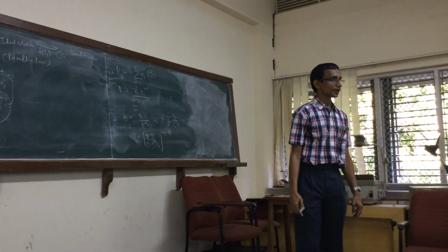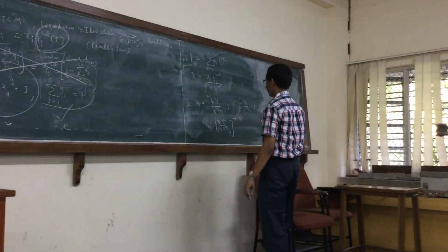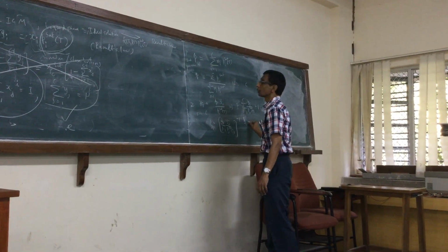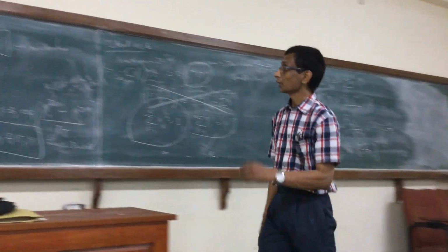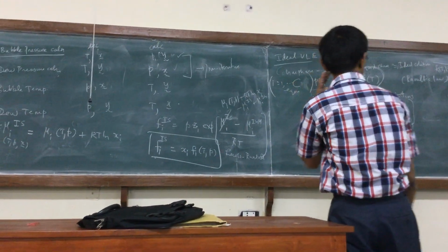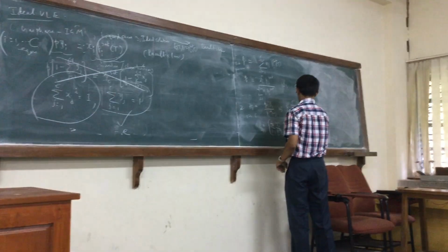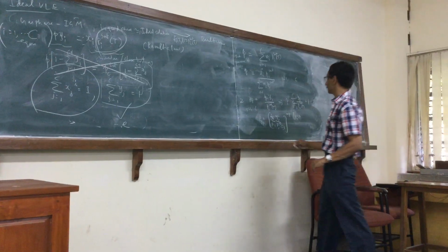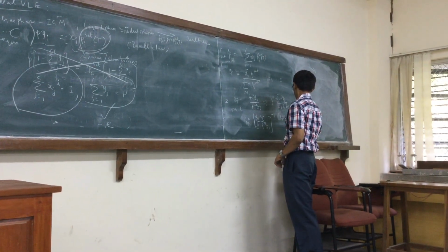Once the specification is given, the dew pressure can be found, and then the xi, which we don't know, I'm sorry, the y is known, the x, which we don't know, can easily be calculated by P times yi by Pi sat.